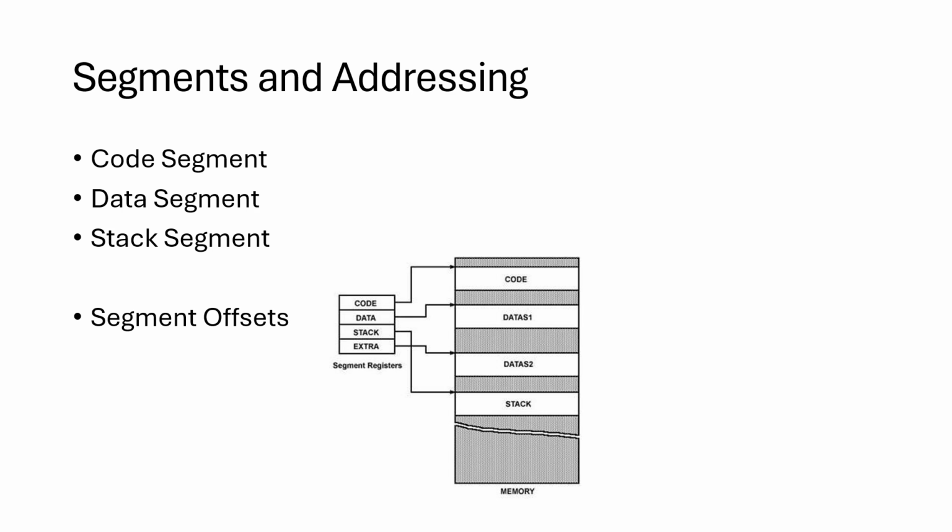In protected mode, these segment registers contain a selector address which is used to find the segment base address from the descriptor table that we had just discussed a couple minutes back. This address is used along with the 32-bit offset to find the exact address.